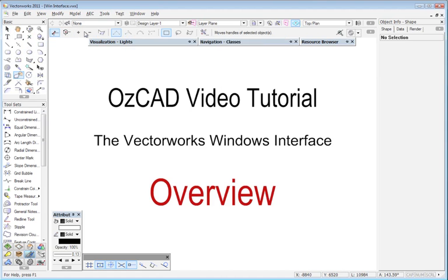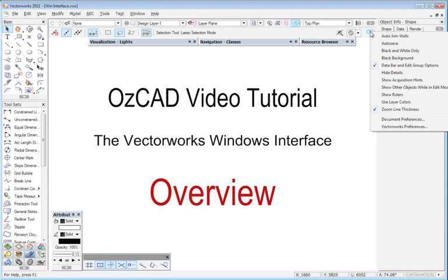And these options are persistent, so that if you use the tool and switch it to, say, this mode here and another mode here, then it will stay on those options the next time you come back to the tool. At the other end here you have the ability to add some commonly used Vectorworks preferences by clicking this disclosure arrow here. For example, auto join, auto save, black and white only, show other objects, show rulers, layer colors, zoom line thickness, and so on.